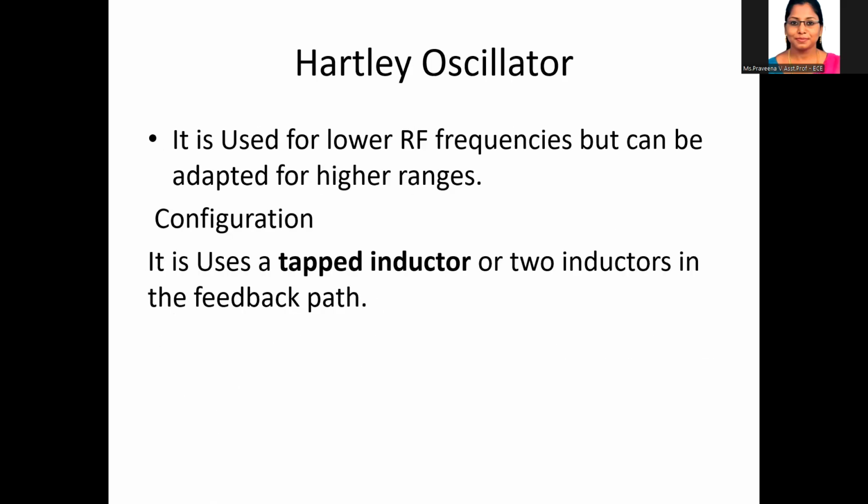And next is the Hartley oscillator. The Hartley oscillator is a popular LC oscillator that is used for generating a sinusoidal signal in RF and communication systems. It is widely used for lower RF frequencies, and it can be adapted for high frequency applications. The circuit design is very simple, consisting of a capacitor and a tapped inductor, or two inductors.